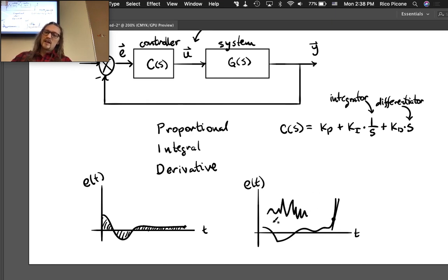If it's noisy, we're switching back and forth between huge positive slopes and huge negative slopes. If you just use the last, say, 2 data points, you're going to get huge positive and negative slopes, and you can see these controllers start to jitter. I'll bring in a controller and we'll play with stuff later on, but you can get jitter, or you can get unstable systems pretty easily with the derivative term. So you have to be a little careful with it, and we'll talk about how to be cautious with it.